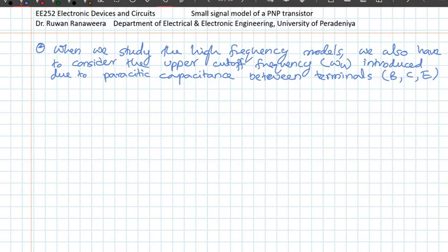The impedance becomes important for us. Normally at lower frequencies they are giga-ohms or hundreds of mega-ohms, but at very high frequencies they can come down to kilo-ohms or tens or hundreds of kilo-ohms. If they are similar to the parameter values in our circuit, then not all the current will flow through my components; some current will flow through these parasitic capacitances and lower my gain.